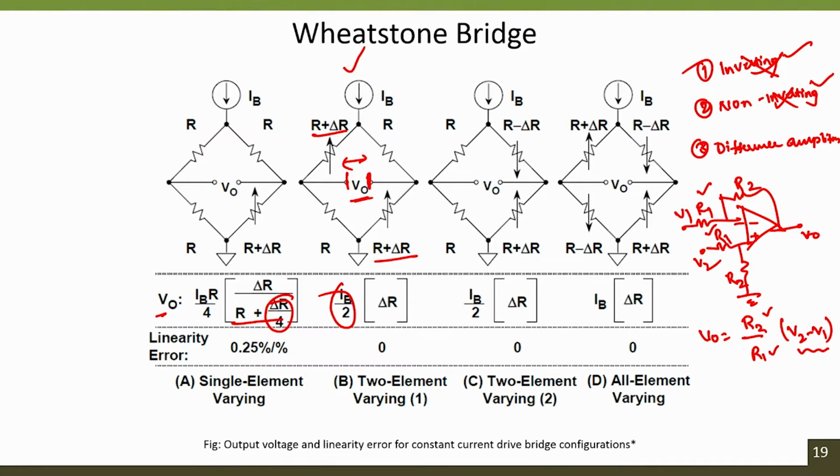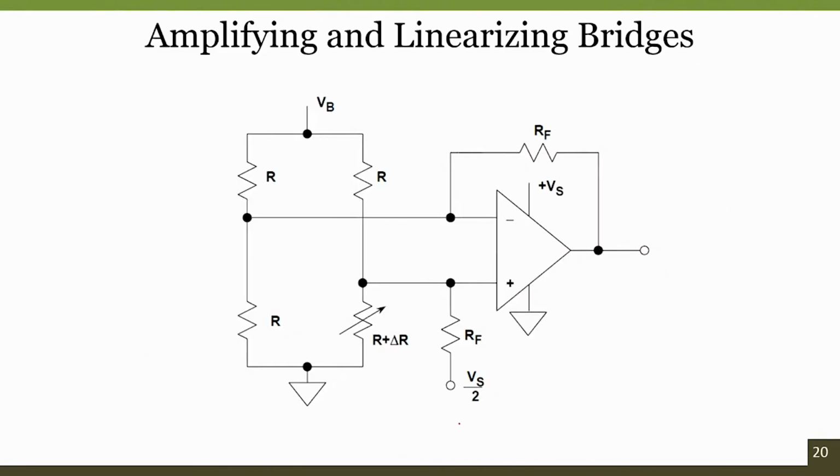Of course, there are other ways of doing it which can avoid the effect due to input resistance, that is the instrumentation amplifier, the 3 op amp based instrumentation amplifier, where even though it uses a differential amplifier inside, because of the topology or the configuration of 3 operational amplifiers, the input impedance is very high. At the same time, the CMRR, the common mode rejection ratio, the ability of the system to reject the common signals, the same signals, is also high. So, this is a difference amplifier.